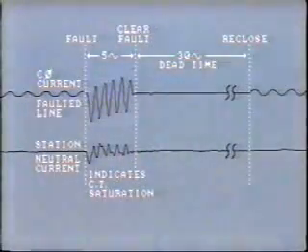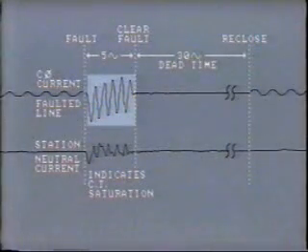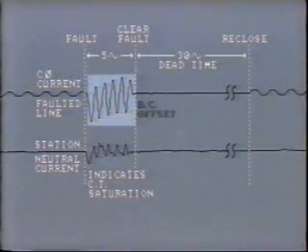In this case, the saturation is caused by the fact that the fault current is not symmetrical. There is much more negative magnitude than positive. This offset in the fault current is called DC offset, and it has the same effect as adding burden to a CT. The CT secondary output becomes distorted and no longer accurately reflects conditions on the system. Now, you'll remember we discussed this problem in PSP 3. But, you might say, if the protection worked okay, why should we worry?